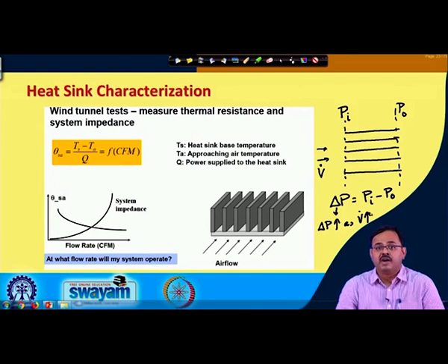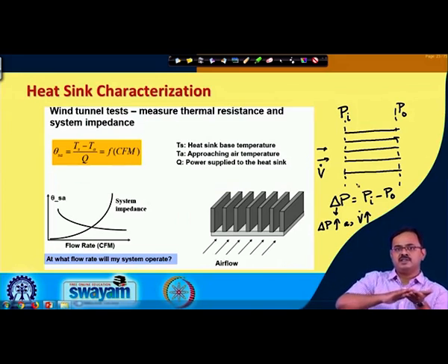Okay. Now, why does this pressure drop happen? That goes a little bit into the flow physics. This is because of frictional resistance at the walls. Because it is a viscous fluid, whenever a viscous fluid flows over a surface, there is the no slip boundary condition, especially at macro scale, where the velocity is 0 at the wall and then it goes up.